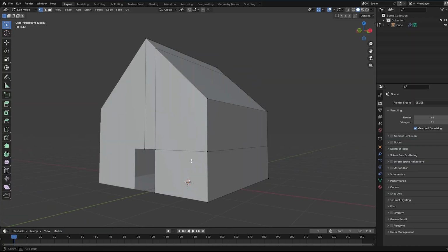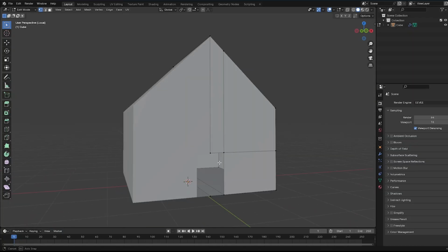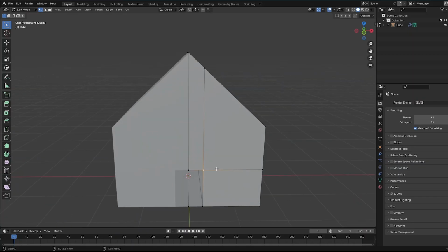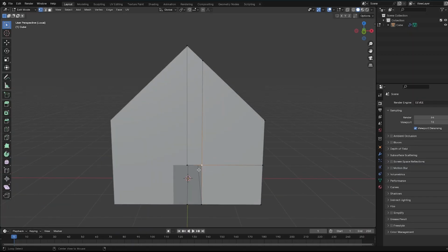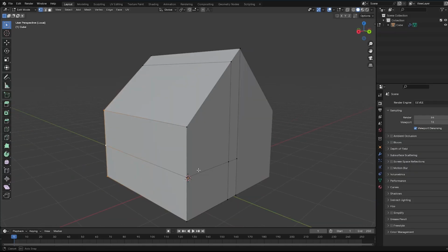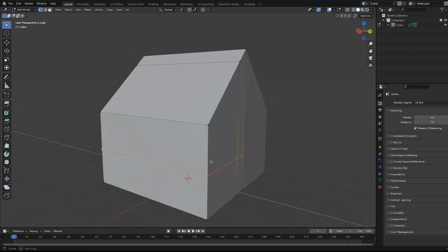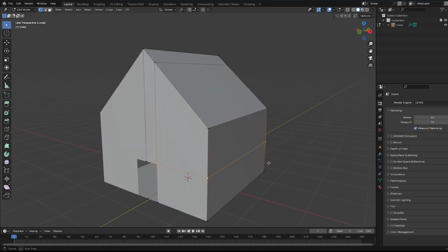Now, let's say I want to change the size of this door right now. So how would you be able to do that? First thing, I'm going to select these parts. You can also press Alt so that it selects the whole cycle over here. You can see it like this. You can see now the whole cycle has been selected.